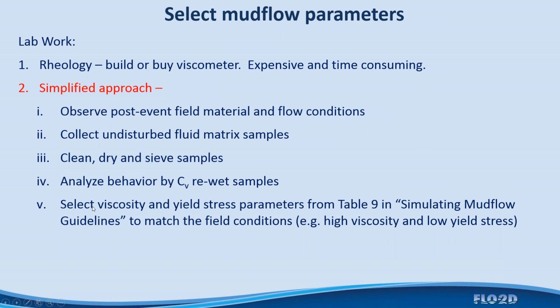sample. However, if you're doing the laboratory approach, I would do this and then wet it, and then put it in maybe a small aquarium or in a tank or something, and slosh it around and see what you get in terms of that first table that I showed you, showing the different behavior for mud flows, mud floods, and water type flood events.